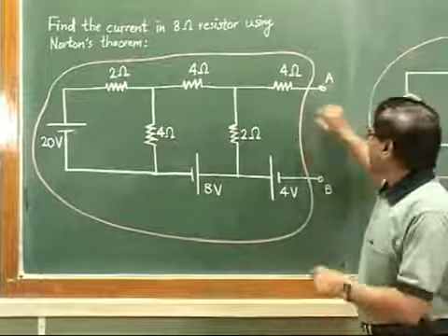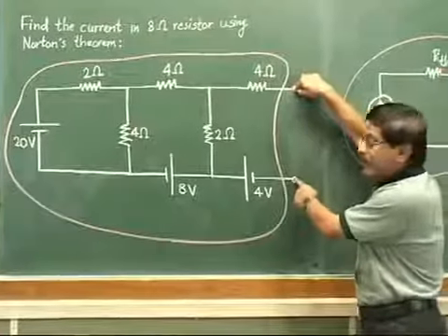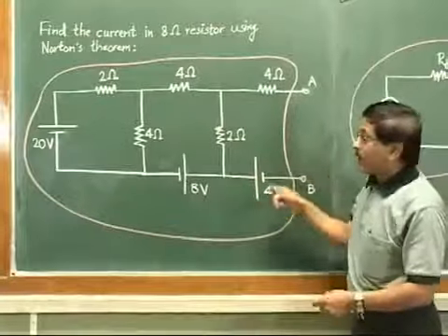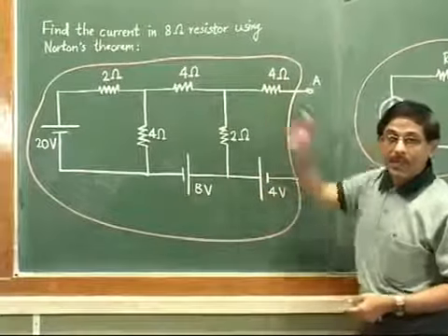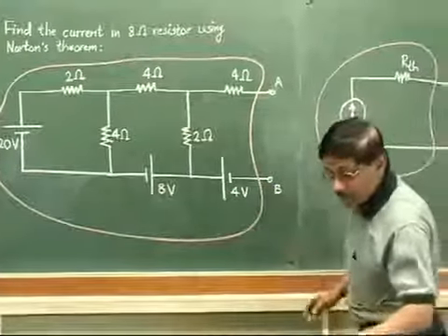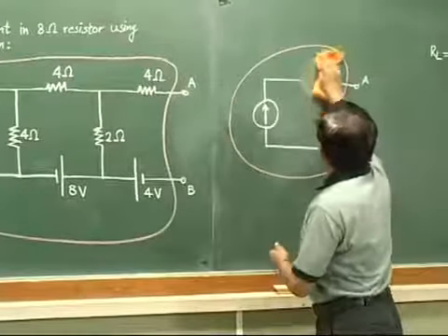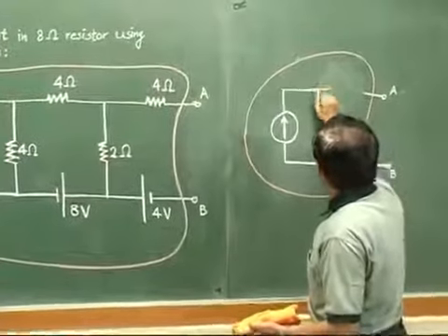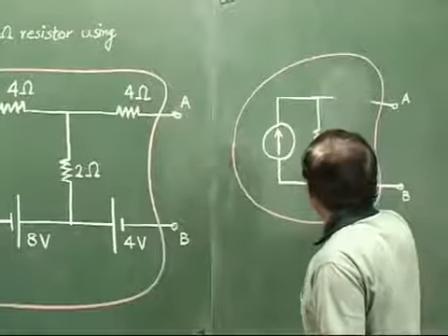So here we find a single value of equivalent resistance given by the entire passive network enclosed in this red line. Then we connect this resistance not in series like this, but here in parallel with the current source. So the things will be represented like this.